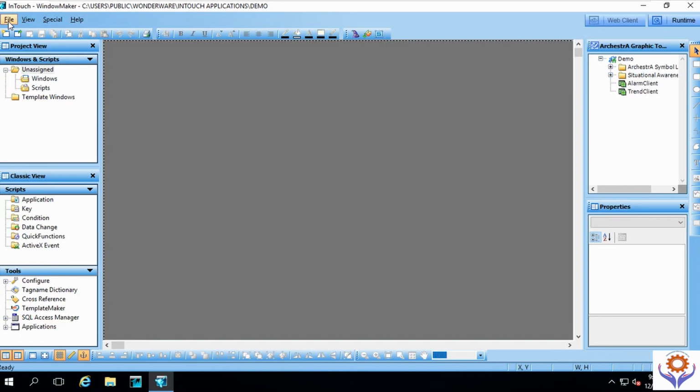Earlier, for the IO server, there is some additional software in InTouch. You need to add that one in IO servers. In the earlier stage, you can use Modbus, and also other software like for Profinet, for Profibus, and for Rockwell's or any others.